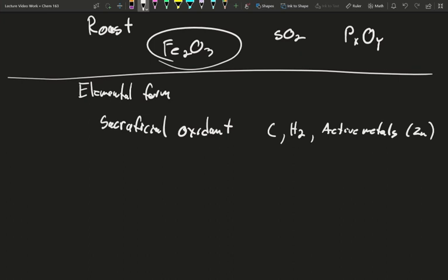This also works for things like aluminum. The modern electrolytic process for refining aluminum from its aluminum salt requires a graphite anode as a sacrificial agent. Large carbon anodes are dipped into a vat of molten aluminum fluoride and other aluminum salts. As a current runs through it, it pumps the electrons into the aluminum and boils off carbon dioxide at the electrode as the carbon takes the oxygens from the bauxite aluminum oxide.